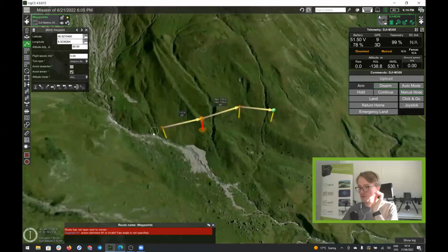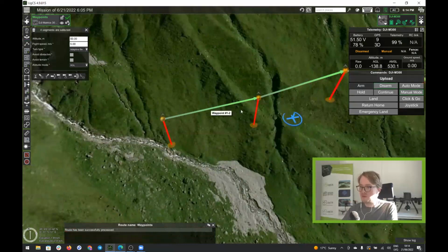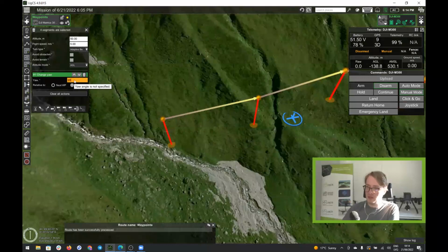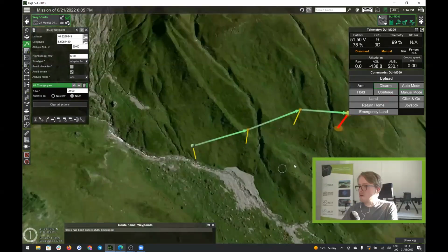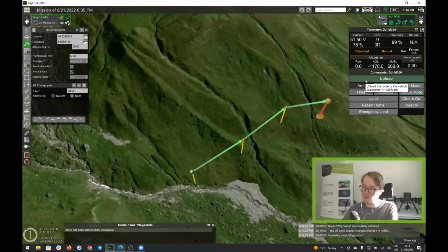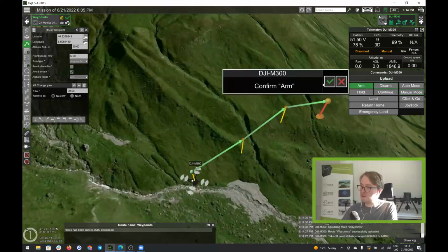I'll quickly explain how to launch the drone on the mission, and then we can go to planning the photogrammetry flight. Also, for example, I'll do set yaw 90, just so you can see this at the same time. Now we have the emulator drone, and to launch it, you need to do upload. But with the emulator, the trick is you need to do the upload two times, so it also adjusts the altitude to where it's supposed to be. With a real drone, you just do the upload once, and that's it. Now after this, you do arm on the drone.